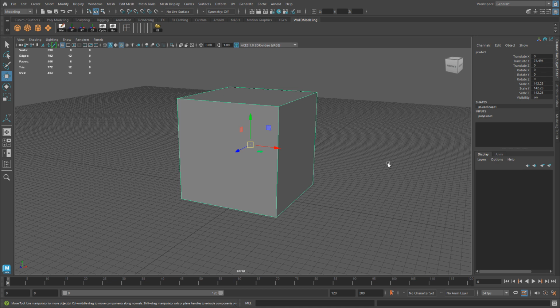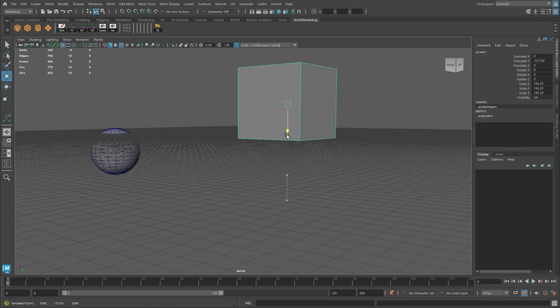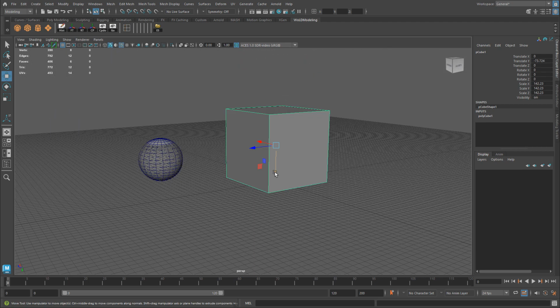And in Maya, they have a specific direction. The Z, or the blue, is front to back. The red, or the X, is side to side, left to right. And the green, the Y, is up and down. And a lot of beginners may create an object and not pay attention to the XYZ gizmo, and it might be upside down. I've seen some objects being created like this. The object is upside down and they begin to model it. And by the time they're done, the XYZ gizmo is in such a weird position that as soon as you see it, you know that this object was not modeled in the correct world position and the correct XYZ orientation.